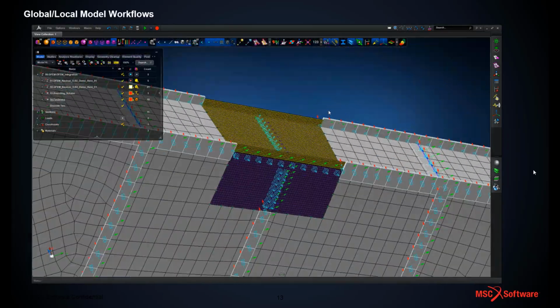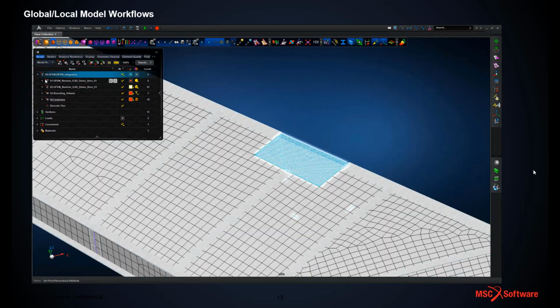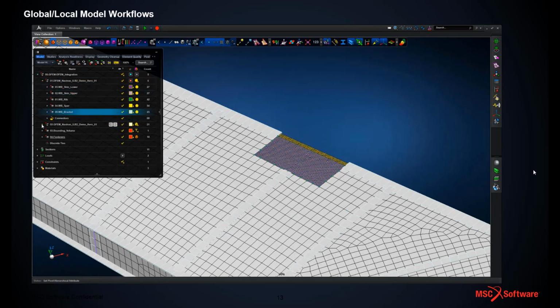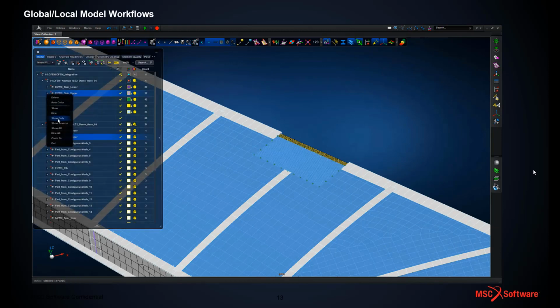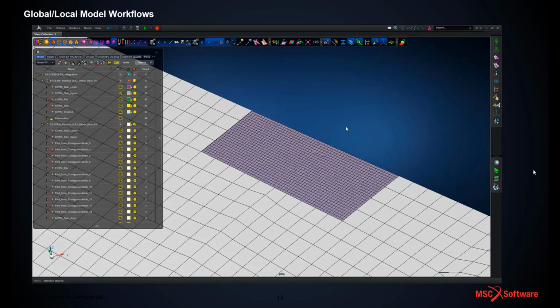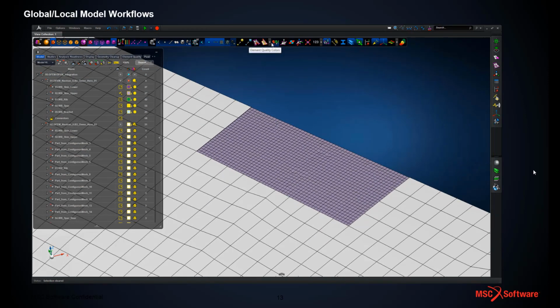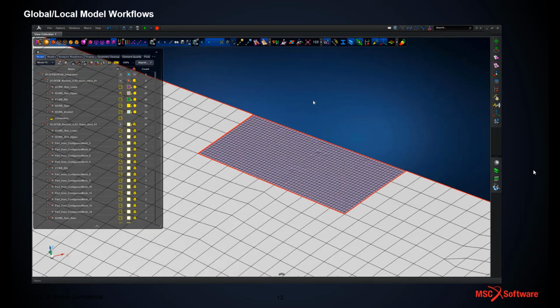So once we've got that local detailed region fully developed in terms of the mesh, the properties and the local fasteners, we now need to tie that into the larger wing box. So again, multiple techniques for doing this, but in this example we're going to look at again how the custom tool palette has been used to develop a simple script which ties coarse to fine nodes together in a manner that gives us load continuity across an interface.